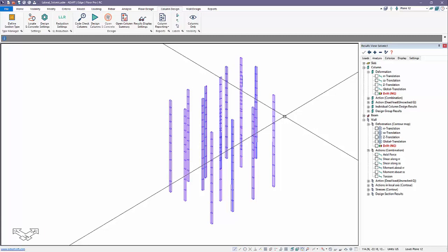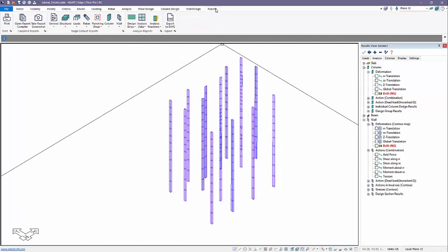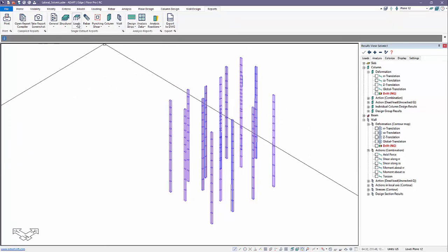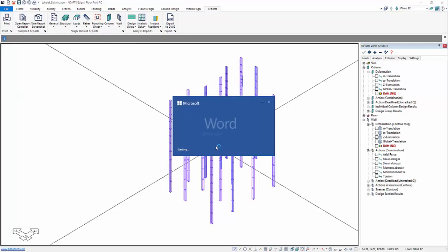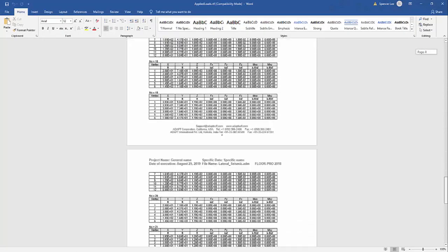combinations. For determining the center of mass and also the story forces that the program actually calculated, we can go to Reports. Under Reports, we're going to go to the Loads option and Applied Loads. And the Applied Loads report is going to actually show us and tabulate the base shear, all of the different seismic coefficients and parameters that we entered, and also the story forces that are calculated. So this gives a reporting of that.